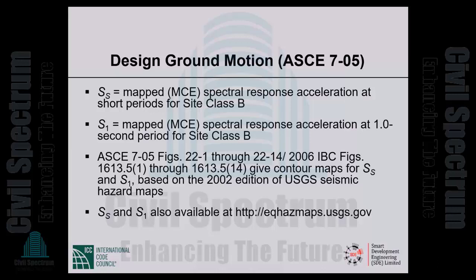S sub 1 similarly is the mapped maximum considered earthquake spectral response acceleration at a period of 1.0 second.